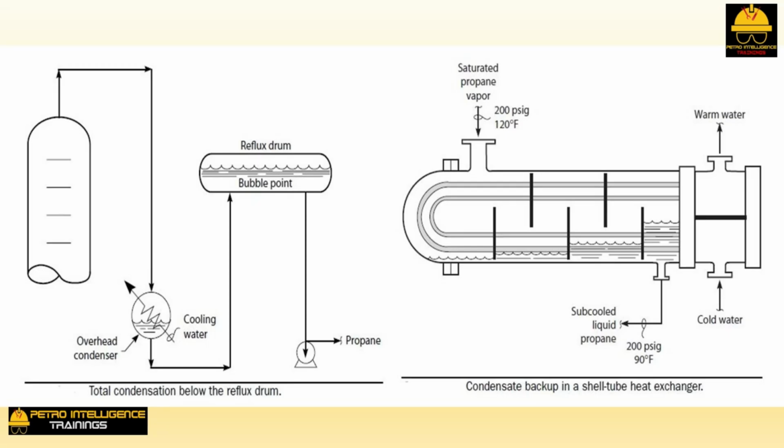Effective condensate backup. When the condensate level in an exchanger increases, the area of the condenser devoted to subcooling the condensate increases. But the area of the exchanger available for condensing decreases. That is bad. When the area of the exchanger available for condensing is reduced, the ease of condensation is also decreased. Depending on the circumstances, one of two unfavorable things will now happen.